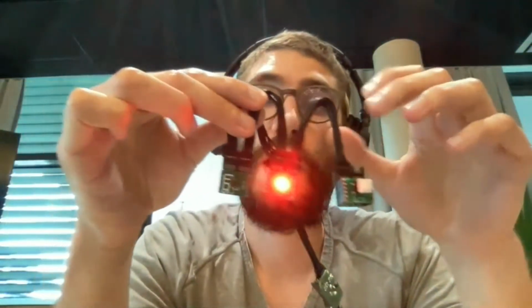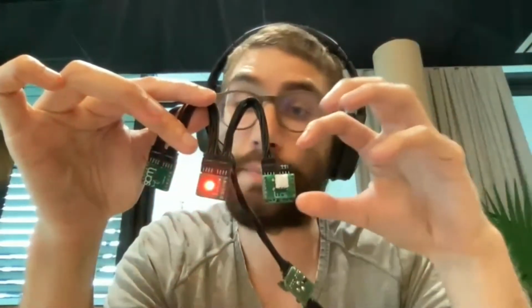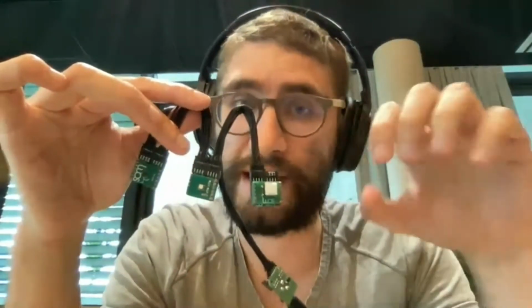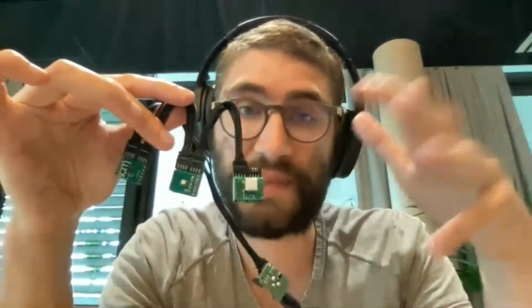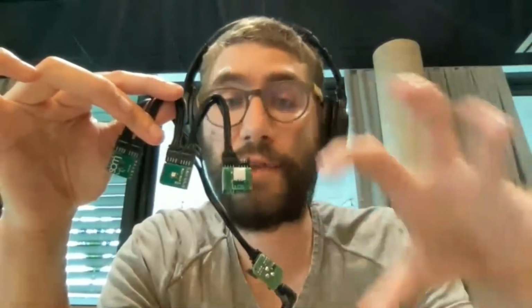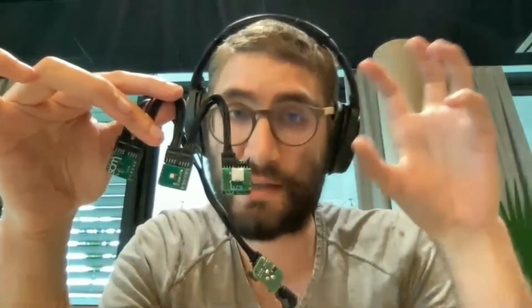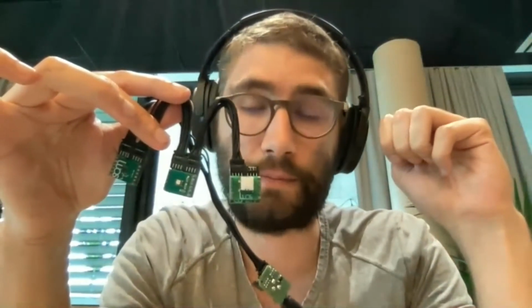In this specific setup, which is a proof of concept, now that we have something working, we can rethink the hardware and, for example, merge all those boards into only one board, and you still have exactly the same software on it. You will have to change the drivers a little bit because you will have to change, for example, the pins for the LED or something like that. But the behavior of your system is still exactly the same. You don't have to change anything because the API of all the services is still the same.